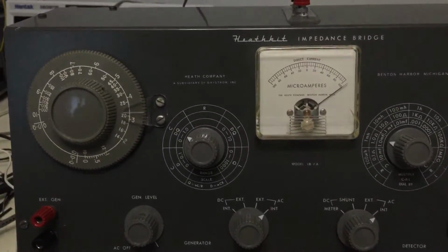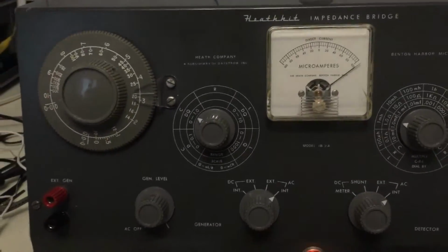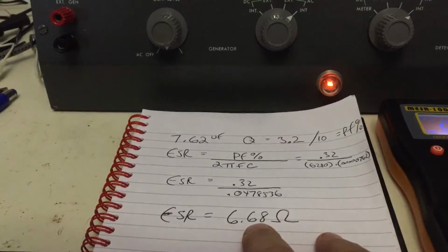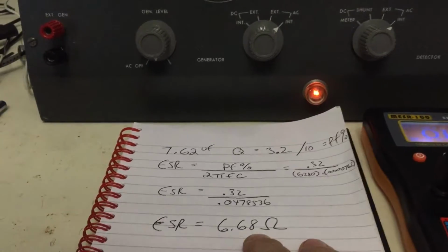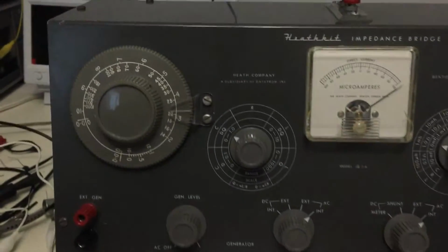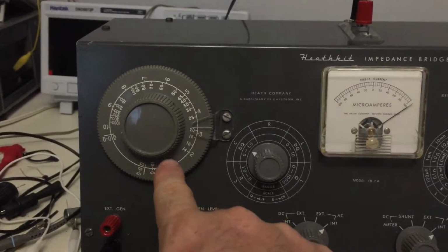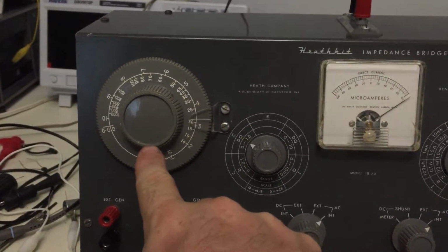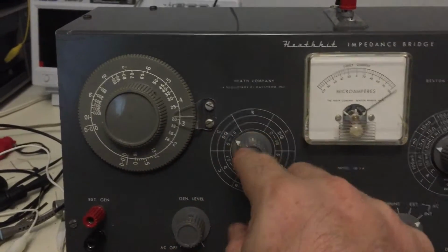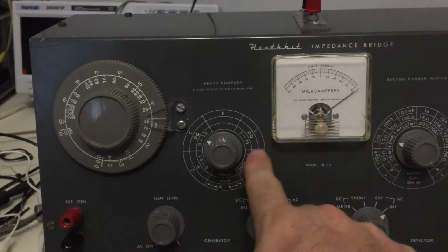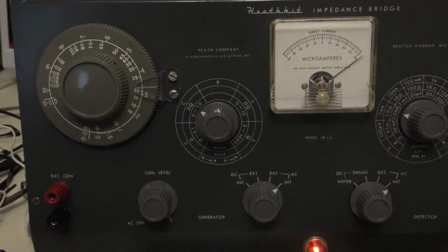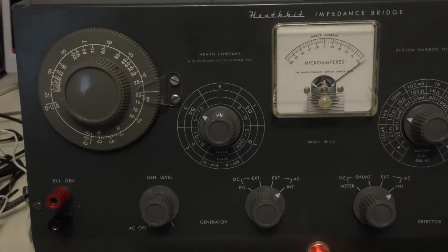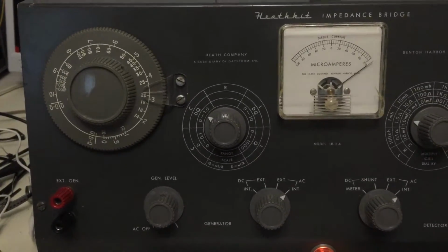So that's pretty cool. I think we could say that if we can achieve an ESR value that's so amazingly close, I think it's off by 0.4 ohms, right? 6.4 something is what we saw on there. Then this knob would have to be really close to derive that value on DQ. And because this knob is close, and because we've proved that out, I think we can move on to inductance. So that's what we're going to see next: measuring inductance on a coil, and dissipation and Q.